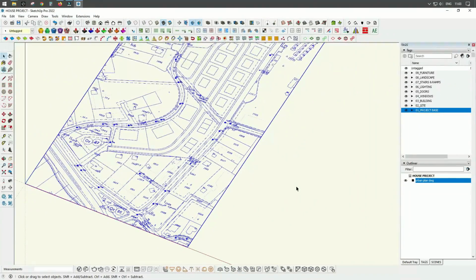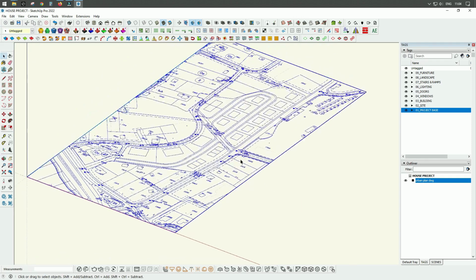The next step will be to assign a tag to this group that we have made, and if you mark the group, now you can see that for the moment the group is untagged. In order to tag a group, I will go to my project browser and see if there is an appropriate tag.